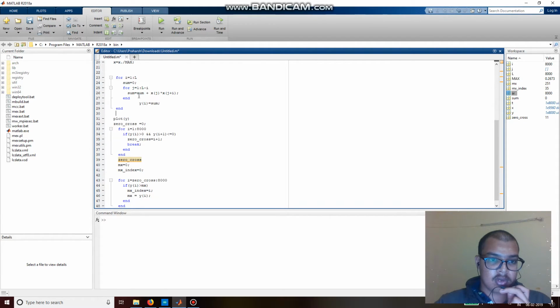So each time we would be calculating the sum of each of the components with the window of j, where j is the window element of the autocorrelation function. So basically, if we are calculating R3, then we are interested in x1 and x4 multiplied, plus x2 x5 multiplied, plus x3 x6 multiplied.